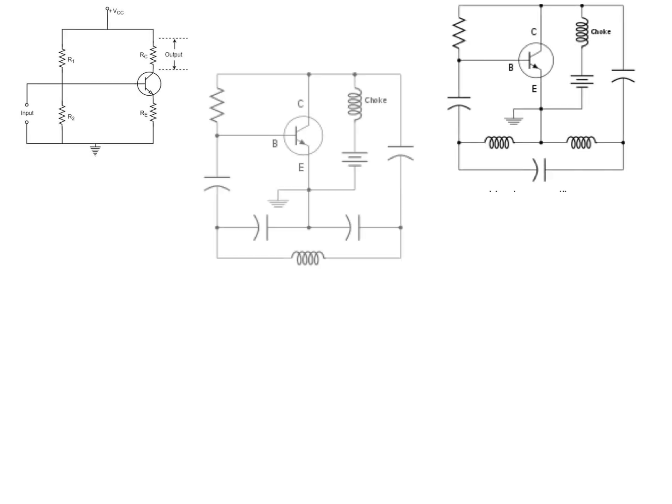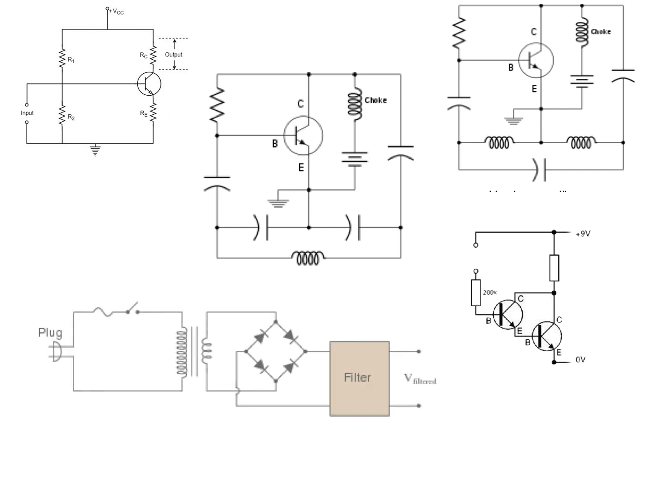Once you feel comfortable with the individual symbols, put away the complex schematics, and start looking over diagrams of basic, simple, widely used circuits. You'll find lots of them in magazines geared to electronics enthusiasts. You'll find some simple projects and related diagrams and electricity experiments you can do at home. Don't study only one type of schematic, such as those that portray only amplifiers. Check into oscillators, power supplies, solid-state switches, RF circuits, audio circuits, and anything else you can find.